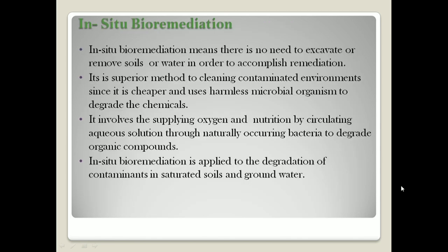In situ bioremediation means there is no need to excavate or remove soil in order to accomplish remediation. It is a superior method to cleaning contaminated environments since it is cheaper and uses harmless microbial organisms to degrade the chemicals. This technique involves supplying oxygen and nutrition by circulating aqueous solution through naturally occurring bacteria to degrade organic compounds. In situ bioremediation is applied to the degradation of contaminants in saturated soils and groundwater.